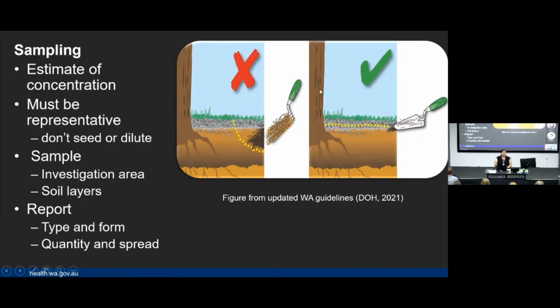One of my biggest beefs, when I was looking at reports, I don't look at them anymore, is non-representative sampling. With taking your samples, even your 10-litre sample, you're supposed to be quantifying how much material is in soil. And it's very difficult to do that if the sample you're taking includes both contaminated soils and not contaminated soils.